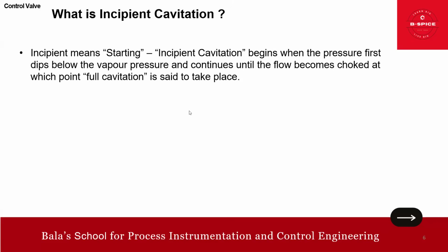Incipient means it's the starting. Incipient cavitation begins when the pressure first dips below the vapor pressure and continues until the flow becomes choked, at which point full cavitation is said to take place. So this is the meaning of incipient. Incipient means starting. So incipient cavitation begins when the pressure first dips below the vapor pressure and continues until the flow becomes choked, at which point full cavitation is said to take place.